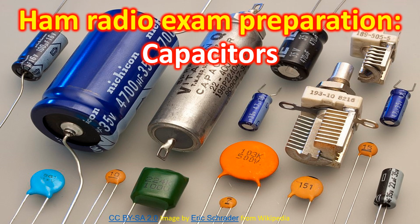There are also capacitors in which the capacitance can be varied, known as variable capacitors, often used in tuning resonance circuits. Capacitance is measured in farads, microfarads, nanofarads or picofarads, depending on the value from higher to lower. High capacitance in circuits for smoothing out ripples in rectified direct current uses several thousand microfarads. Farad, being a large unit, is seldom used. A typical tuning capacitor in radios may be rated at 500 picofarads, 500 pF.